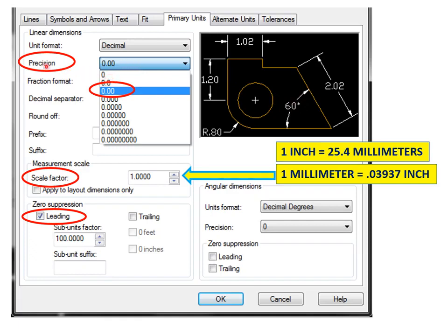If you also want to change the number of decimal places, you go to Precision, go to the drop down, and if you're creating an inch drawing, so drawing with units of inches, you typically want to go with 2 decimal places for all dimensions. If it's a circle where you need precision, accuracy, then you may go with 3 decimal places or 4 decimal places. But for inches, typically you go with 2 decimal places for all your dimensions. And then from there you can deviate. You can go to 3 or 4 decimal places if needed. Remember, the more decimal places, the more accuracy, the more expensive the part gets.